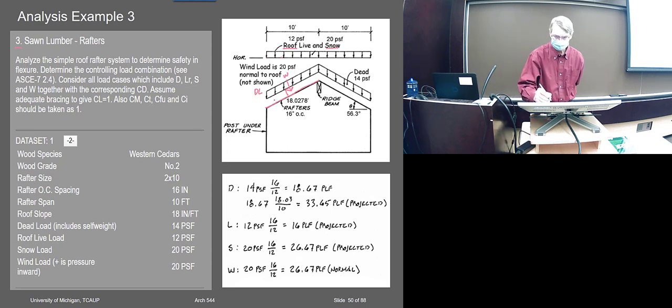So in calculating the wind load, it's a load on that full length, like that. So I've got three different types of loading. And the best thing, normally, if you can do it, it's convenient to convert the loads into projected loads. So this dead load I could convert into a projected load just because it's still straight down. I just have to shorten it to the projected length.